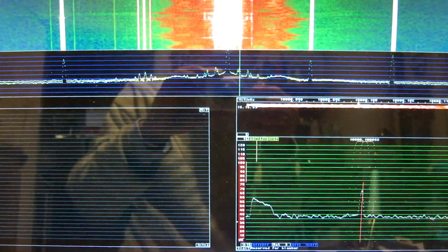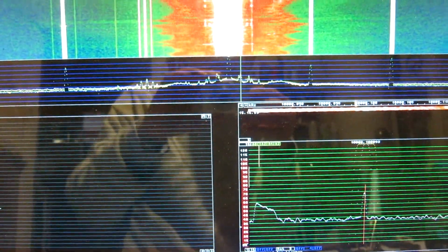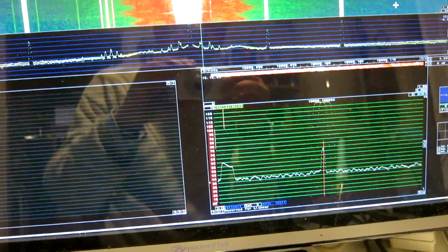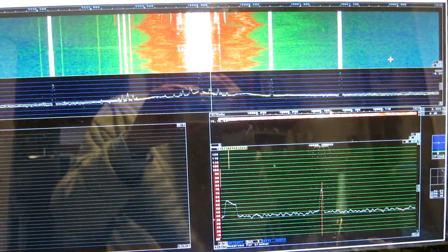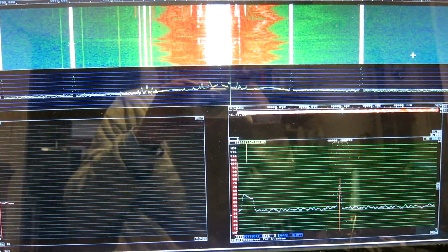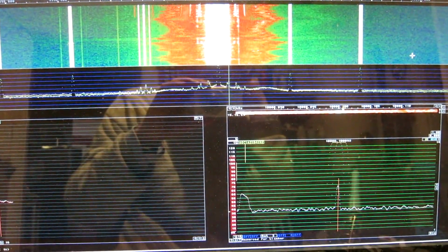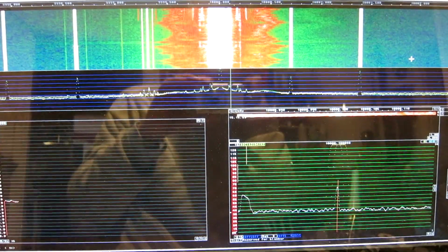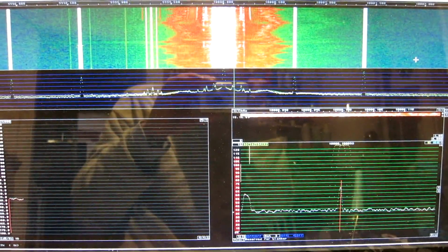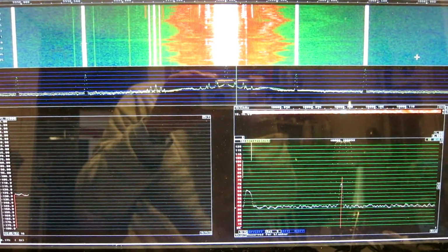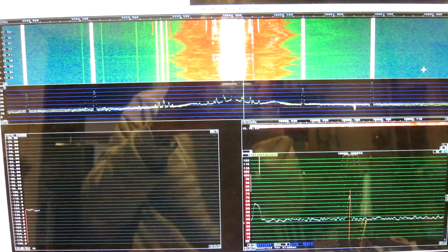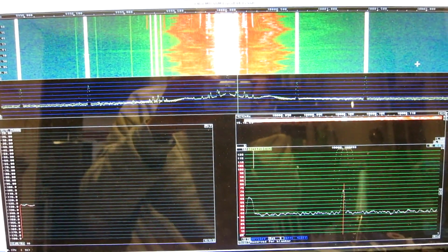This is another thing to worry about, the magnetic sensitivity of crystals. I guess the mechanism is that there is steel from the socket up to the crystal, and that steel is magnetic, and the fields will cause it to vibrate, and that will cause strain in the crystal, and that will affect the frequency. Or it will cause modulation at least.